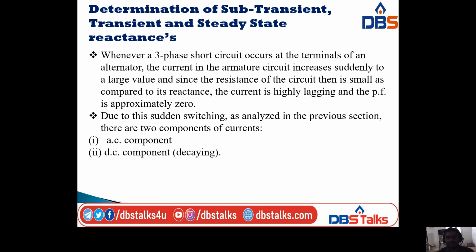Whenever a three-phase short circuit occurs at the terminals of an alternator, the current in the armature circuit increases suddenly to a large value. Suppose we take a three-phase alternator and a short circuit occurs at its terminals. That means the current in the armature circuit increases, not in the field. It increases suddenly.